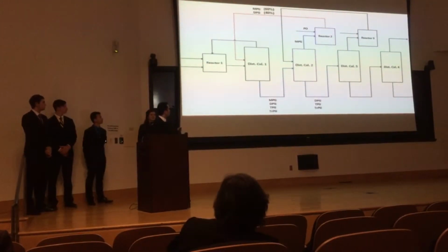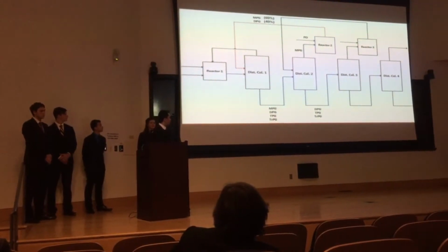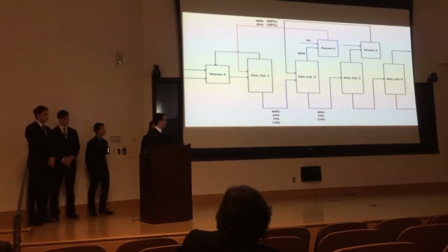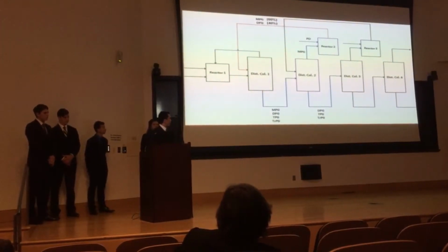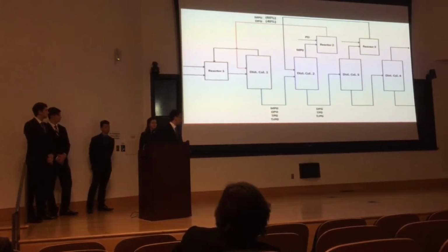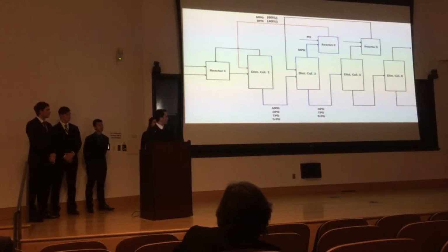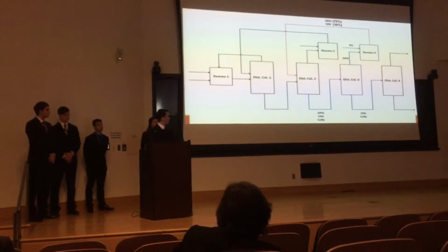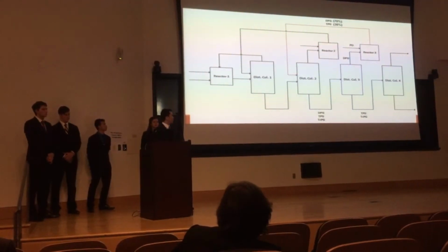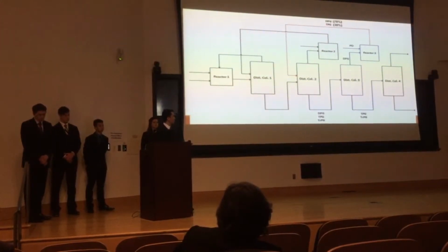And then we feed that into the first distillation column, which is then further separated downstream. Next, at the bottom of distillation column number 2, we have dipropylene glycol, tripropylene glycol, and tetrapropylene glycol, which is then fed into the third distillation column. From here, at the top, we want to separate dipropylene glycol and then further react it with propylene oxide in